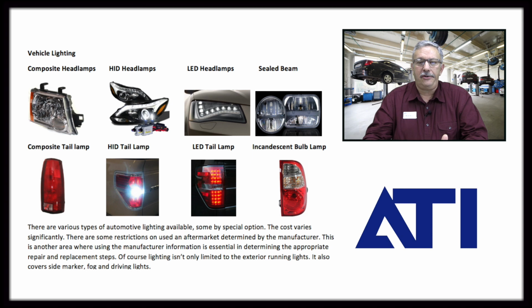Now, why does it make a huge difference? A couple of things I want to go over at this, because this is really important. You're going to be asked by insurance companies to use used parts. And in the case of the Audi, this is extremely important, because an Audi that's produced in the US does not use the same electronic and electrical parts as an Audi produced in Europe.